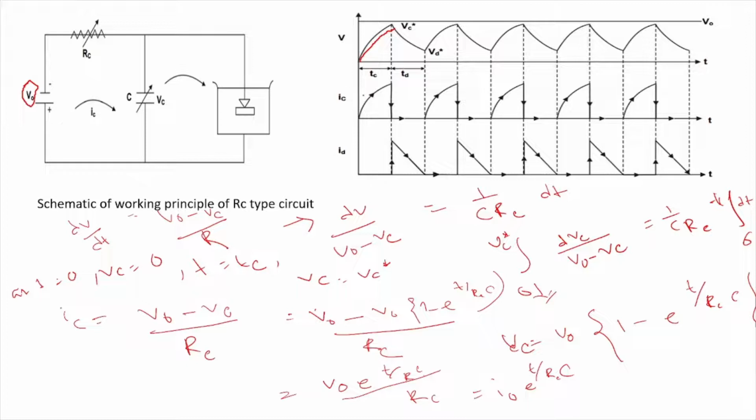Okay. Similarly, if we come down to the Ic by t plot, here during the on time, the charging current is not there. You can see here, no charging current. Okay. So if we come down to the Id by t plot, we'll see that the machining current is there. This is on during that discharging phase. So the machining current will be on during the discharging phase.